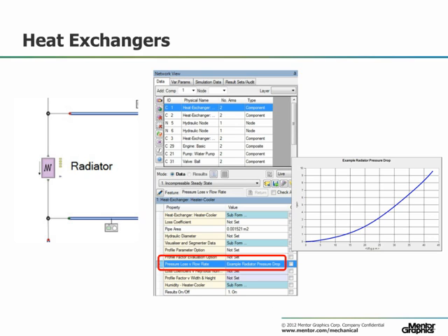Heater-cooler components are used in the network as a simplified version of our primary heat exchangers, specifically the radiator, heater core, and oil cooler. At this stage, thermal behavior for these components is not going to be modeled, only the pressure losses associated with them. To characterize this, the heater-cooler requires a flow area and either a loss coefficient or a pressure difference. In this case, pressure drop versus flow has been added to each one to characterize its losses.